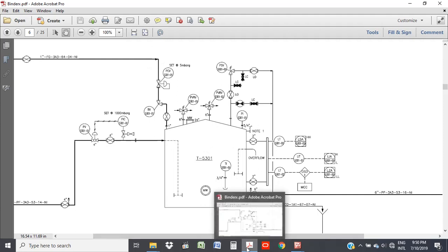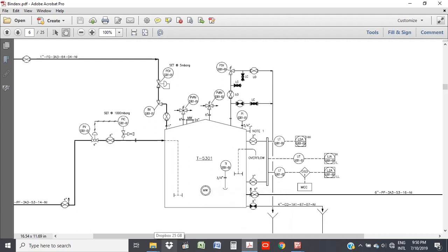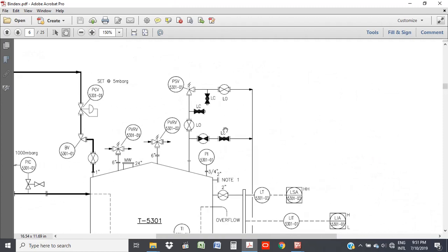There's a key with the supervisors, which is used when maintenance or any work is supposed to be done. Those valves are very critical, and that's why they lock them open or closed, because you don't want people inadvertently opening or closing them. It could lead to major process upsets, it could lead to fires. So you have the keys, and then you have to get a PTW, a permit to work, to actually open those valves or close them.